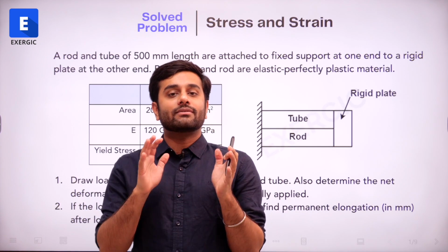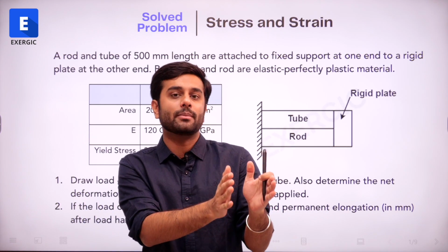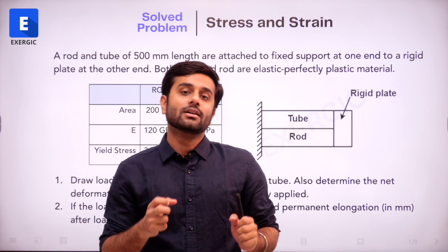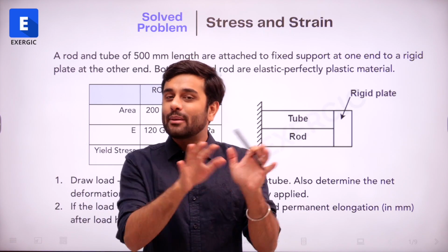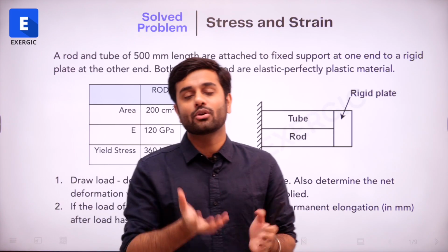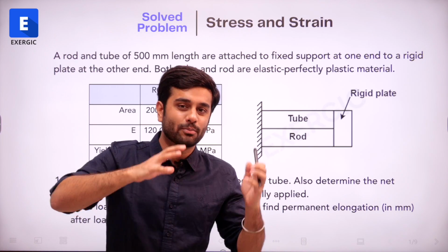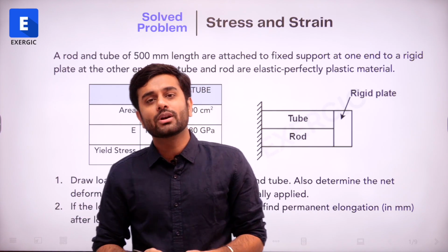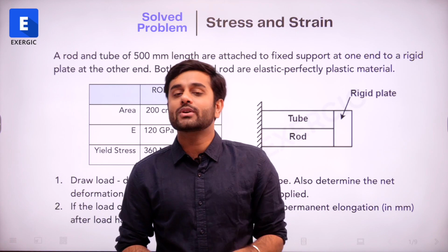But when you have a specific case, a specific loading, a specific dimension or body given to you, and then a load is acting on that, then the load deformation curve can also be used because the dimensions are not changing now, right? We are not trying to compare this body with some other body, or the property of this body with the property of some other body. In such a situation, load deformation curves are good to go, right? They are in fact used for such situations.